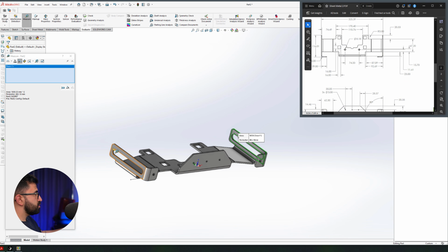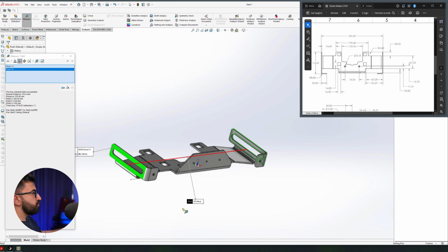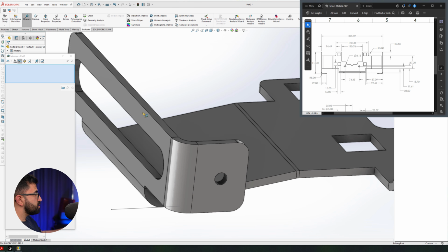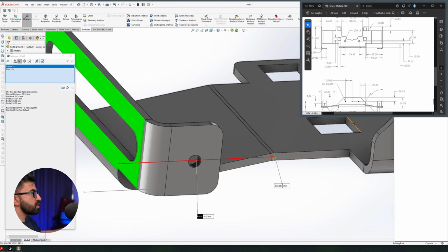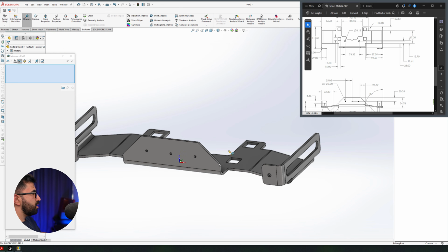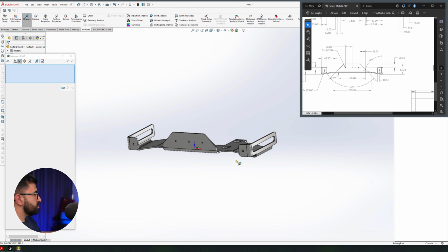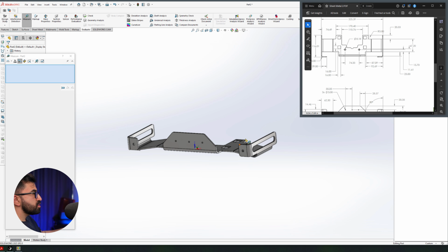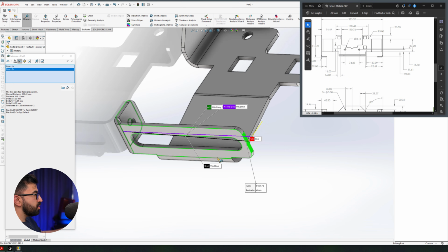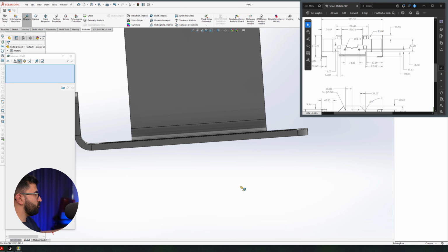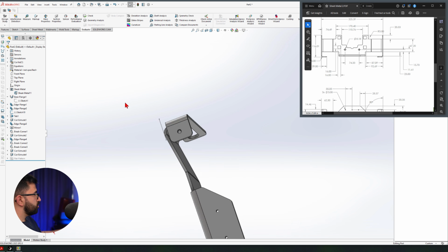Now from this surface to this surface, I get 325.4, which is 325.39. Okay, how about this surface to this line? Oh, 62.31 is now correct. 62.30. I'll take it. And let's just do one more measurement, a couple more measurements. This should be 140. It is. This should be from here to here, 116.01, 116.12. Why? Okay, I take it within the tolerance.